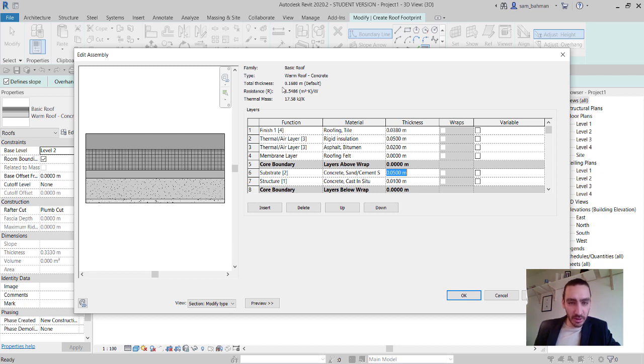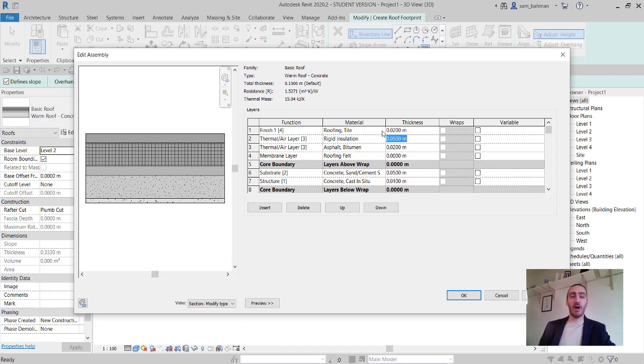And the thickness of this one is around 0.16 now. So what I'm going to do is just decrease the thickness so that I can reach 0.15. So I'm going to put this at 0.2 and see what happens. So as you can see, the thickness is all 15 centimeters now. We're all fine. And the top layer, I prefer to have with the concrete, since I wanted to make sure that all these walls and slabs, or let's say the roof, are all going to get joined together. So it will just convey this feeling that it's all a box. It's all something which is engaged together, right?